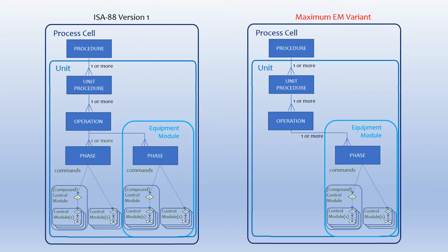By assuming that units must be built only from equipment modules, the whole intent of ISA-88 was bent out of shape to fit this false restriction. All the phases that should belong to the unit were assigned to non-processing equipment like inlet lines, because they had to go somewhere, right? This model is no doubt familiar in some organisations.